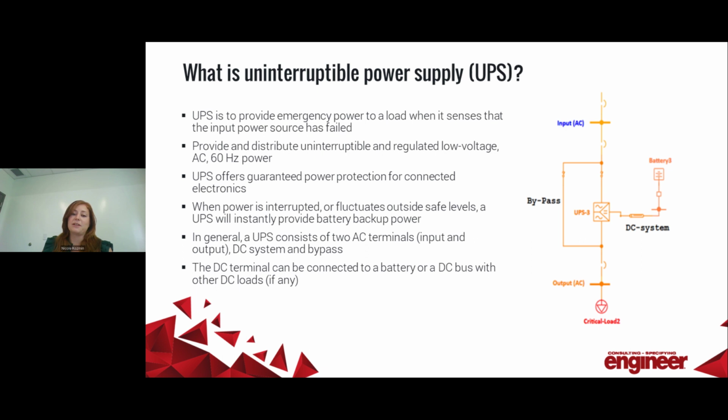Upon loss of power, most generation facilities require time to come up to normal speed and voltage, and that time can be anywhere from 5 minutes to several hours or even days. So upon loss of normal power or power fluctuation, the UPS is instantaneously available with a regulated AC output.